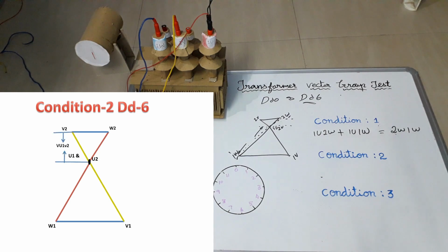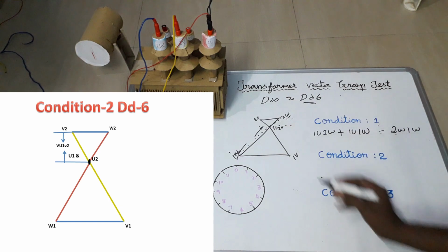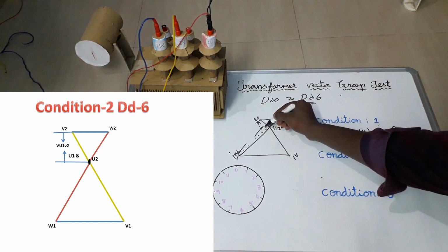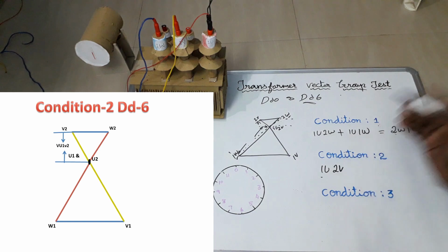For condition 2, I'm going to do the same thing towards here. That is, I'm going to check the voltage between 1U and 2V.